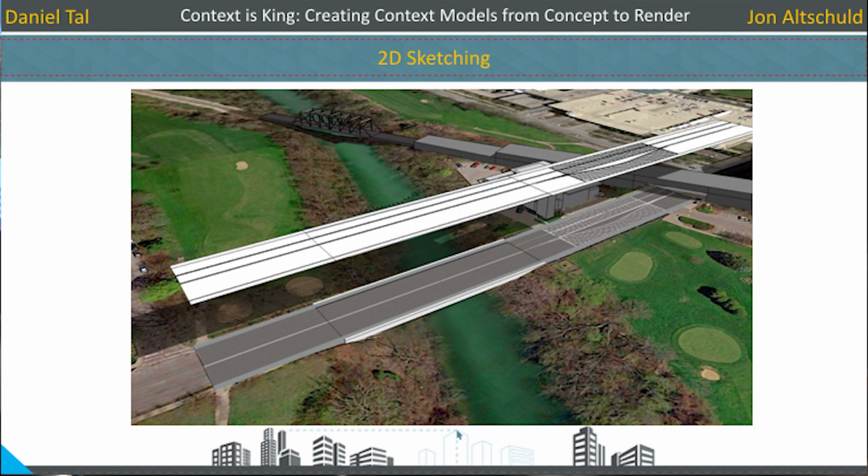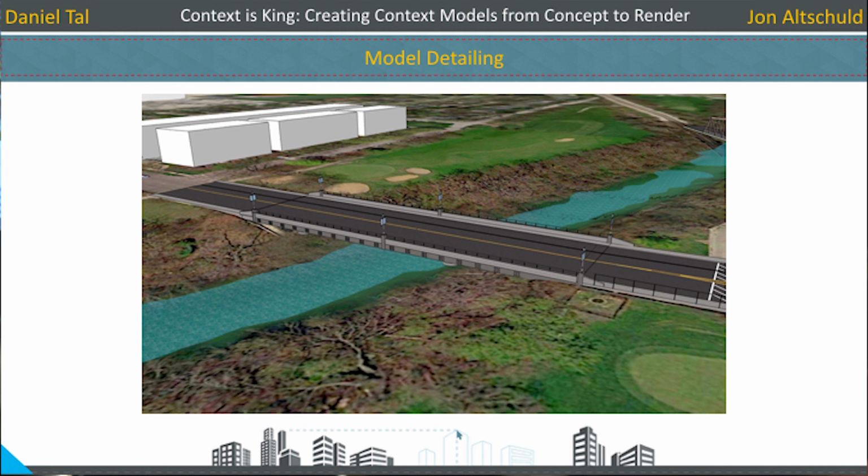And then on top of it, because the terrain data elevation here is higher than these, this is actually broken up into 3 separate planes. So what did we do? Here's the flat one. We added color, then extruded the walls, extruded anything we need to on the walks, broke this up into 3 different pieces, and then rotated it into place so it sits on top of the terrain. Add more detail to the rest of the bridge, so fencing, lights, whatever else might be important in terms of the bridge itself.